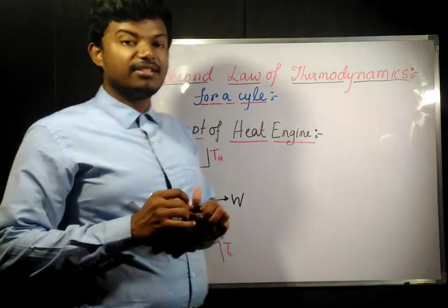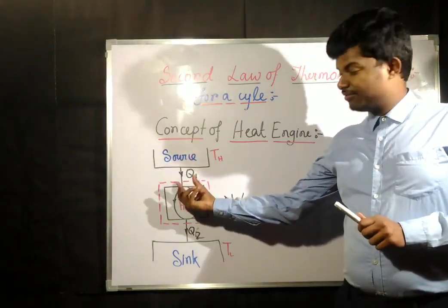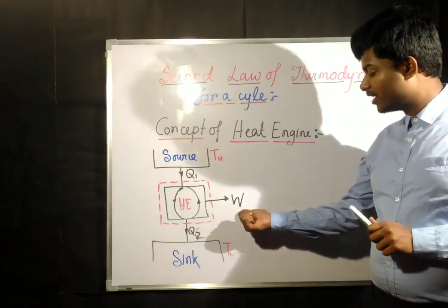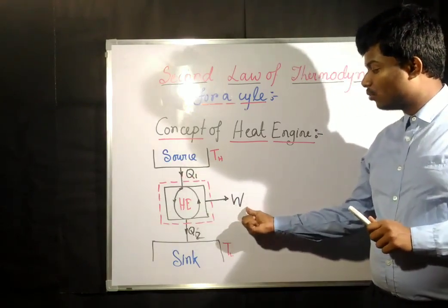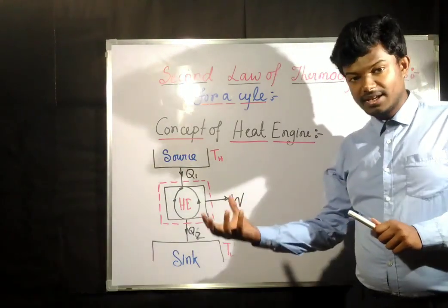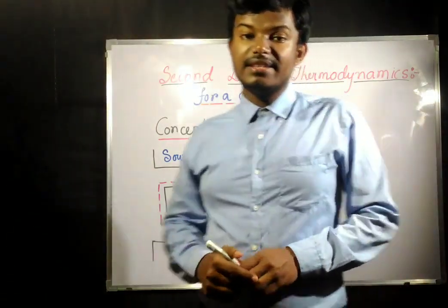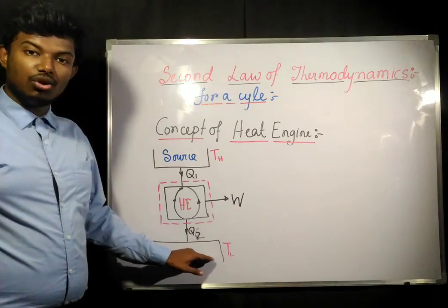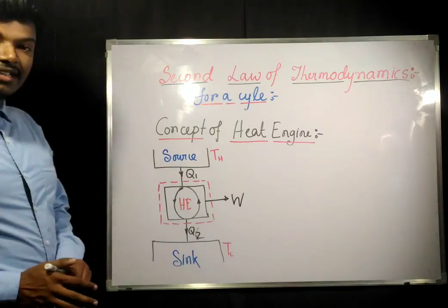Okay, that means what is happening: an amount Q1 of heat is coming from a source. After that, a part of that heat is going to get converted to work, and the remaining heat, after converting to work, is going to get disposed to the sink, or released to the sink, which is a thermal reservoir at lower temperature. Okay, this is the concept of a heat engine.